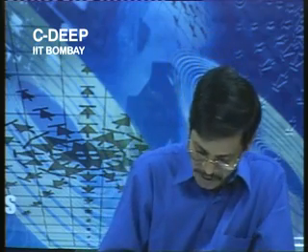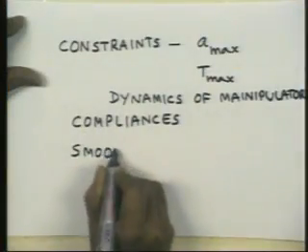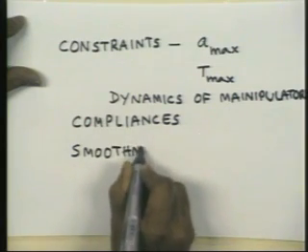In any case, any non-smooth motion, even if the links are not compliant, any non-smooth, jerky, rough motion is undesirable, because it could set up vibrations. It could lead to quick wear and tear of various mechanism elements. So you want a certain type of constraints to be placed on the smoothness of motion. Okay, so we may have certain smoothness constraints.